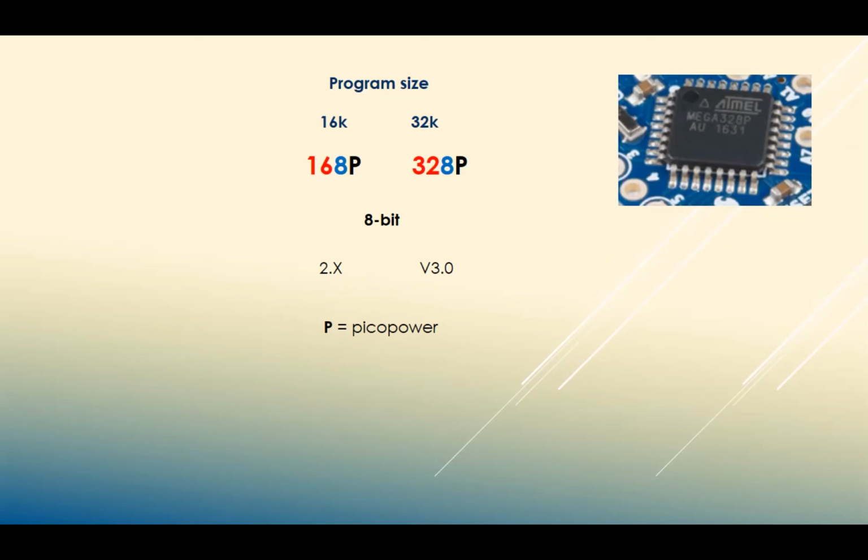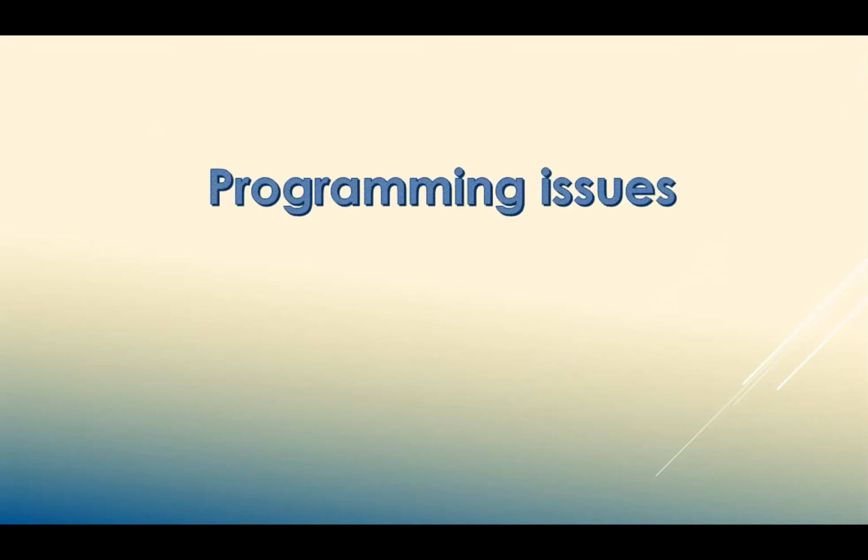So hopefully that unbundles some of the specifications. As long as you see that it's got a 328P in its specification, and a USB at one end and a 6-pin connector at the other, you're pretty certain that you've got yourself a proper Nano when you're looking at the specs. So that covers selection of trying to buy one.